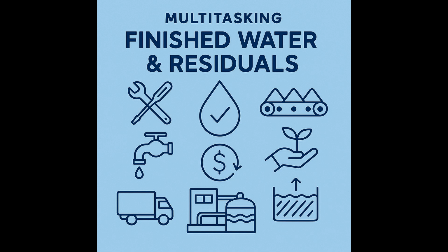Okay, step one, raw water intake. Water comes in from the river, lake, whatever. And boom, right away you've got residuals: screenings and debris, things like sticks, leaves, algae, maybe some trash. That stuff gets screened out and usually just goes to a landfill. Sometimes grit removal happens here too. That sand goes off for disposal.